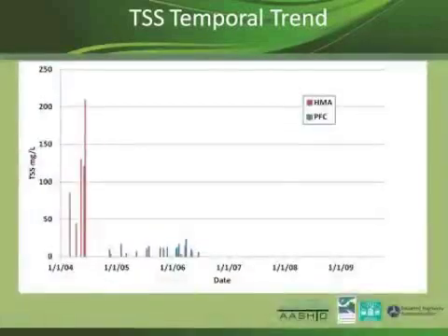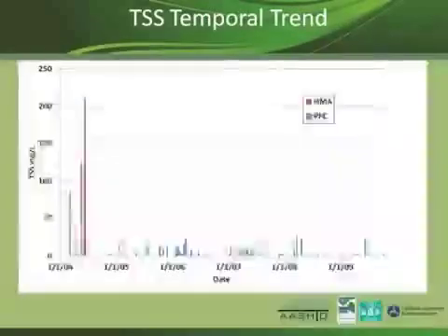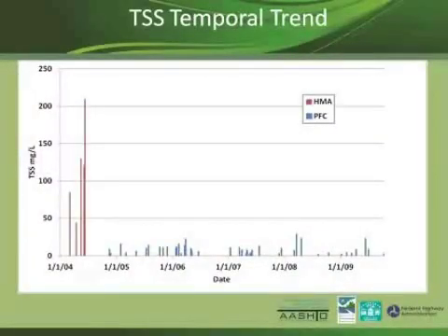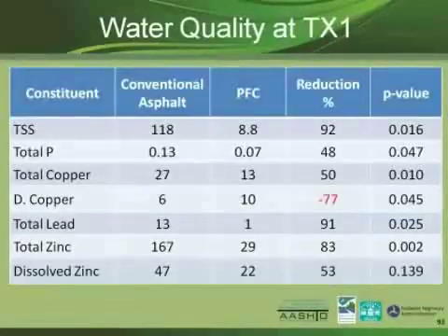And that's the data that's appeared now. You can see what happened in that additional year, that it kept going, and we kept thinking, well, it's going to clog and the water quality is going to get worse. And we said, oh, TxDOT, give us 3 more years. And so we continued going along, and you can see that through the whole length of the study, the quality of the runoff, at least for suspended solids concentrations, maintained an average concentration of less than 10 milligrams per liter. And finally, TxDOT said, enough is enough, and why don't you find another project to work on? So the next slide.